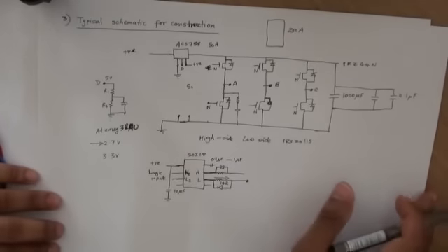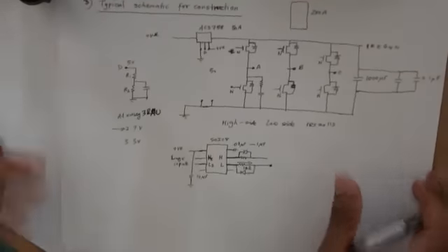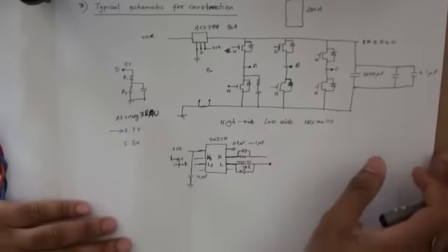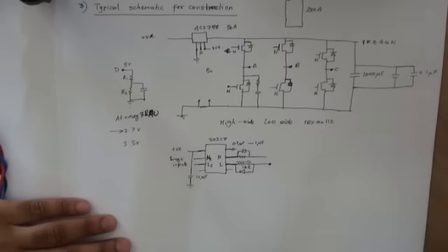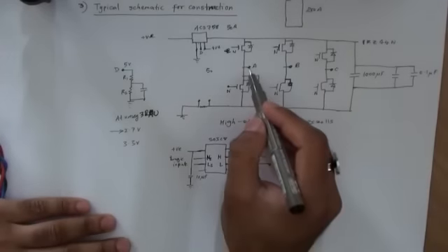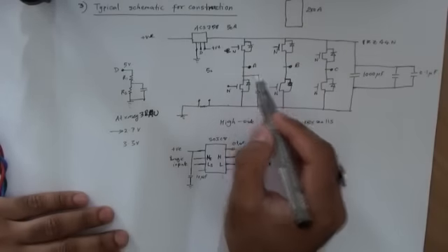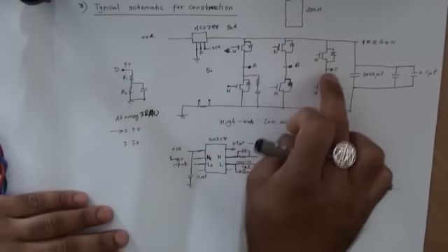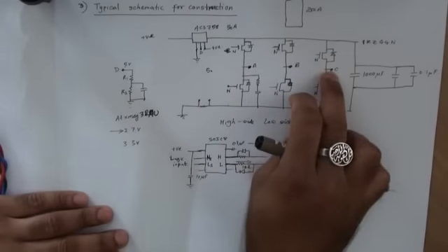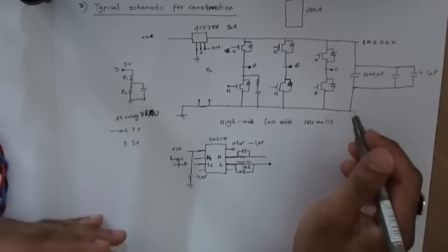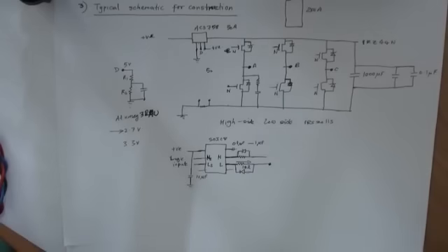There are a few other voltage divider networks you have to consider. For instance, when you are doing back EMF sensing, as discussed previously, you need to look at the back EMF on these phases. As you fire 2 phases, you want to look at the third one and keep monitoring it. As it crosses 0, that's when you know that you're ready to fire the following pulse to the other 2 phases.